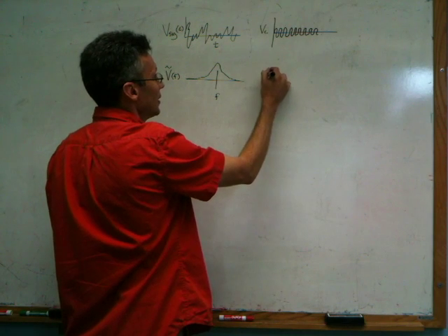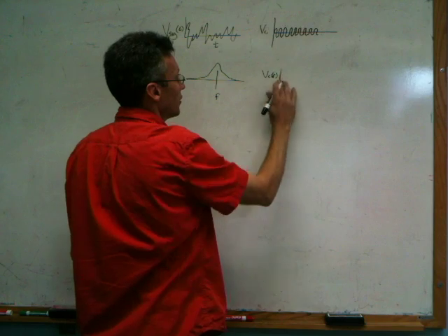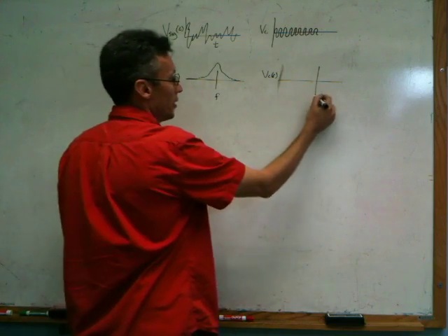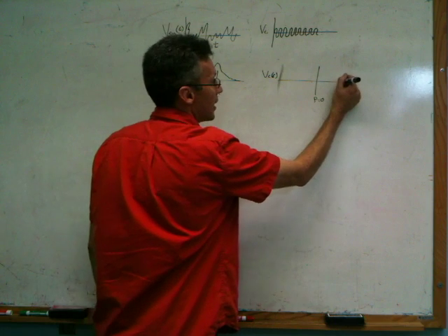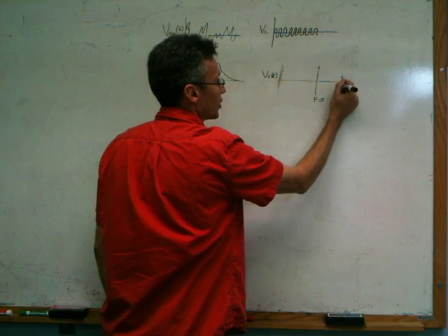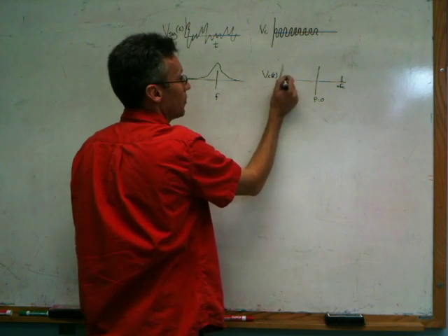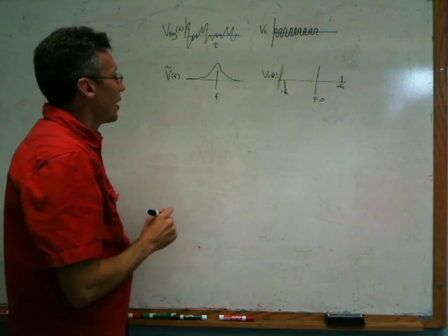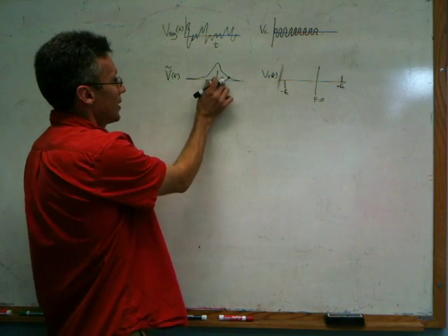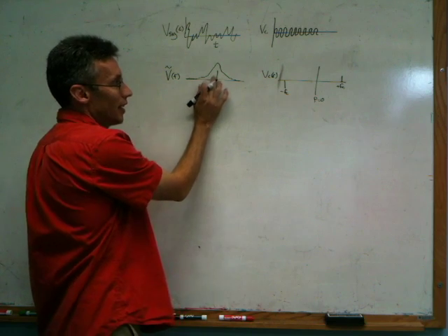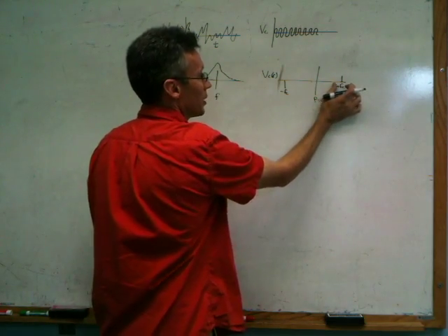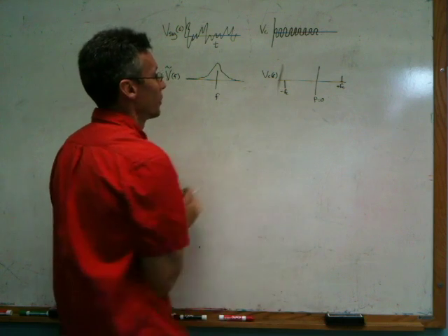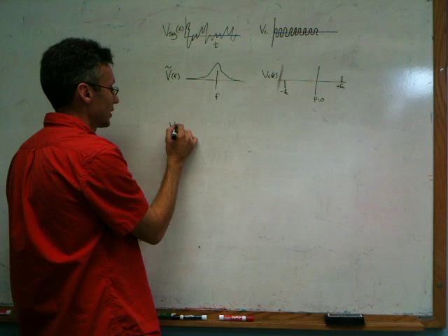Likewise, we can look at the frequency domain representation of our carrier wave. So if this is zero frequency, a sine wave has a Fourier transform that is a delta function at plus and minus the frequency of the carrier wave. And so if we want to take the information contained in this signal and move it in the frequency spectrum to be centered around the channel corresponding to this carrier wave, we do that by modulating the signal.